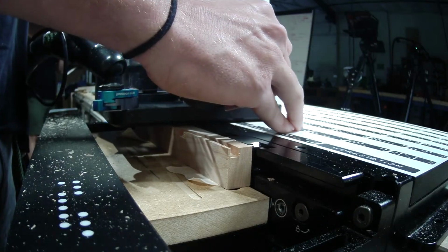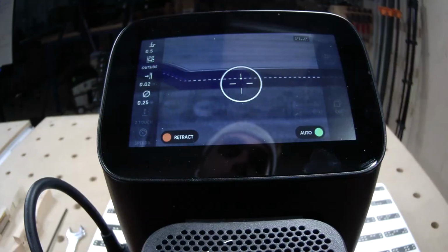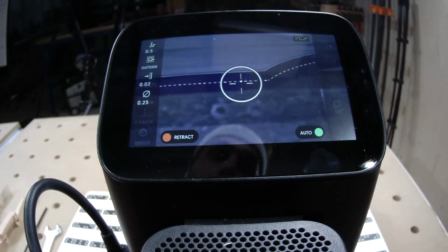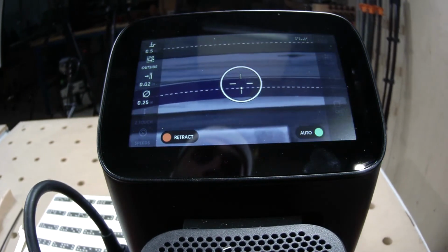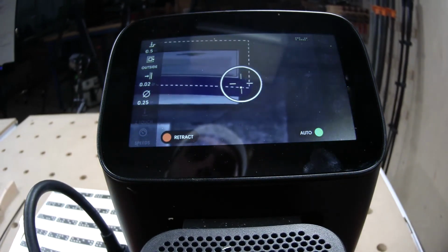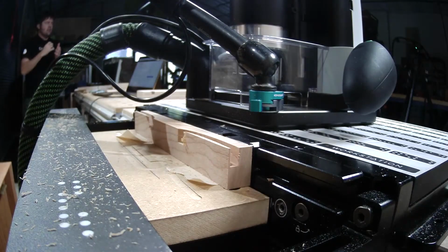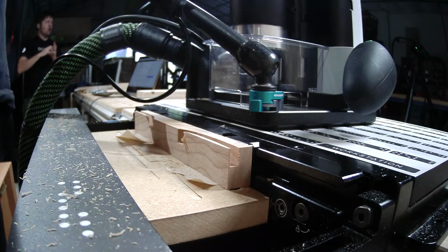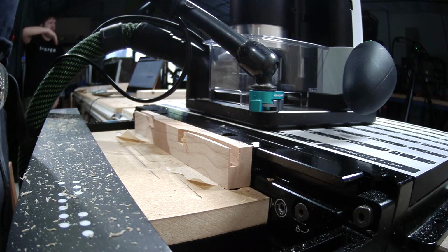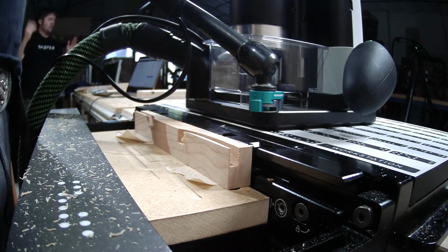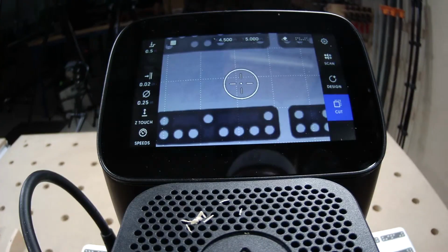But that means if he was to continue driving down without doing that tiny offset, once he hit his maximum flute depth, it gets quite difficult to cut because there's no flutes there clearing material. So what you end up with is the cutter scuffing against that surface, and it can end up getting so hot that it actually damages or burns the wood because it's spinning at 10,000 RPM or more. So that's how he's approaching this.